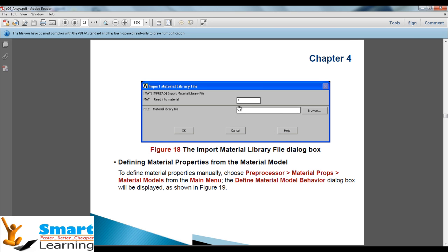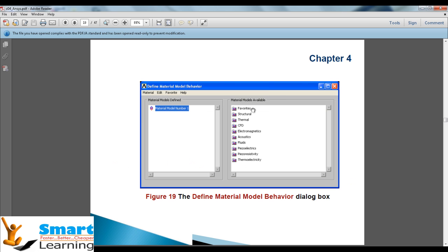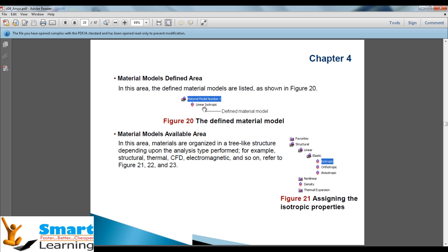You can locate the material by assigning a number and by connecting to the material library. This particular principle I will show directly here. If you see the material number, when you configure the available material, that particular number will be integrated to it. If you are talking about isotropic material, orthotropic material or anisotropic material, certain principles govern these materials.